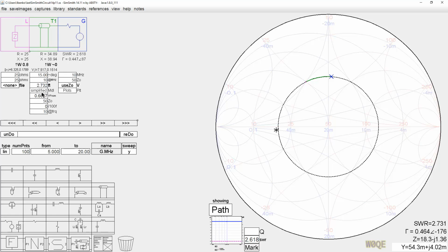There are parameters up here that we can't adjust by dragging. This dragging component on the piece of transmission line only affects the length. We cannot affect the velocity factor. We cannot affect the impedance. Those are values you have to enter either by putting a value in there, typing it and clicking outside, or by being in the field here and doing things like these arrows.